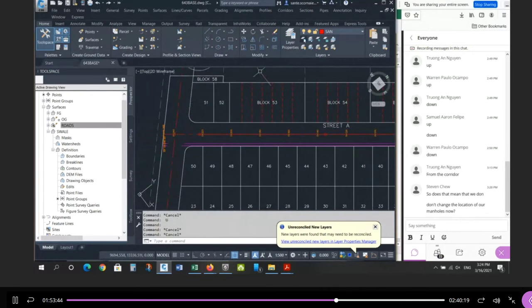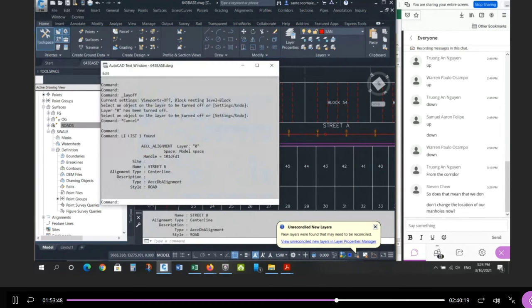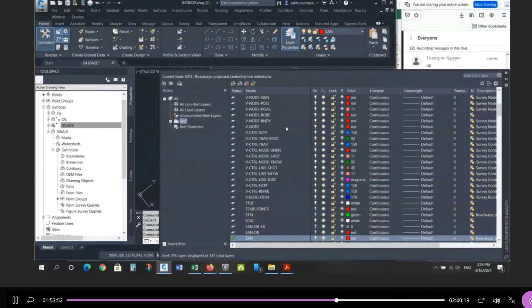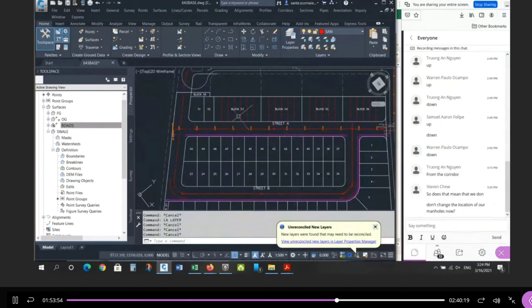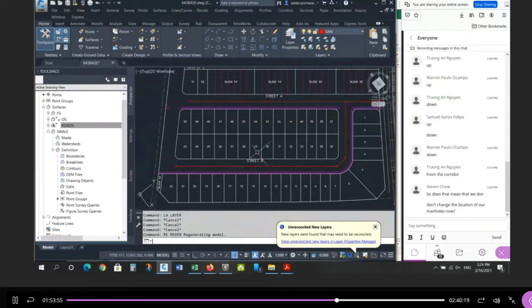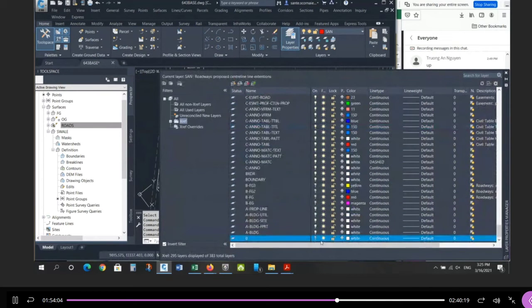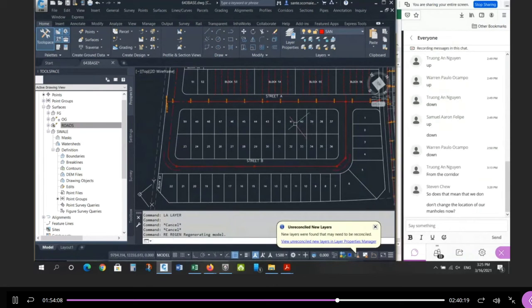I think I can turn the center line off. Maybe layer 0. I'm going to turn off layer 0 just temporarily. Oh no, it won't work if I do that. Okay, I'll just use the maintenance holes. Oh, there it is. It did turn off. Okay, so there's the sewers. You want to digitize it. It might not work with 0 off because the pipes by default go on layer 0. So I'll turn that back on.